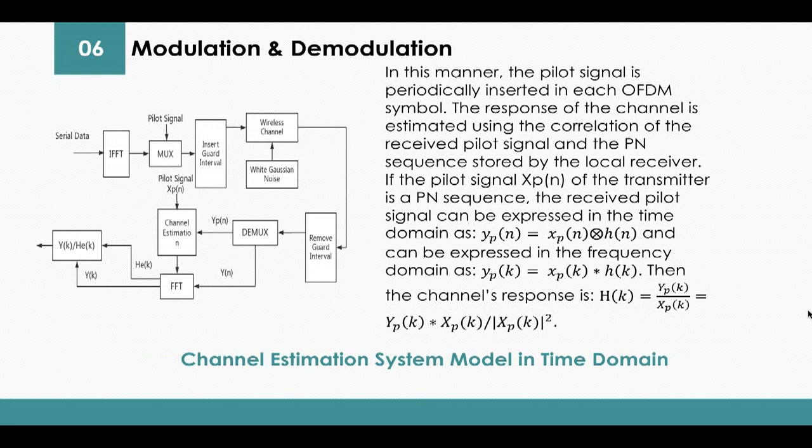And this is the channel estimation system model in the time domain. In this manner, the pilot signal is periodically inserted in each OFDM symbol. The response of the channel is estimated using the correlation of the received pilot signal and the PN sequence stored by the local receiver.